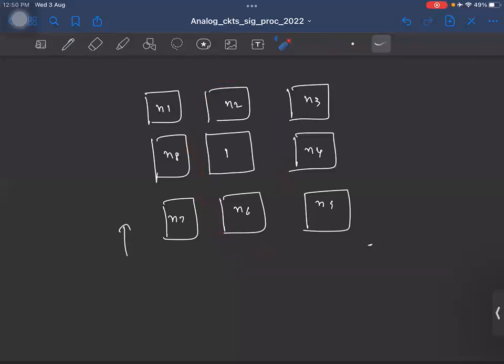This way you make sure that on an average, the operating environments for all the diodes are similar, because all we want is the one diode and all the 8 diodes to have the same condition. Now this one diode is at the middle, kind of at the average. Here you have some diodes which have higher temperature, some have lower temperature. So on an average, if you sum up all 8, they'll match this guy.